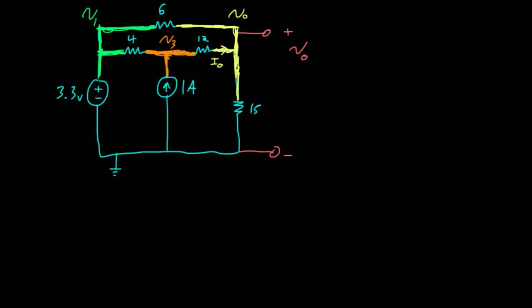So I've got 3 different voltages, and then one last thing, can't forget, is that I have my ground node. So my ground node here is all at the same voltage, and that voltage happens to be 0 volts. So that's my ground node, and this is 0 volts because it's connected to ground. So that's the first step. I just identify all of my nodes. I personally like to color in the different nodes, so if you have color pencils, it might be a good idea. It keeps everything very visual, I guess.